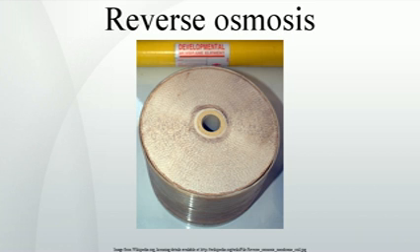The process is similar to other membrane technology applications. However, key differences are found between reverse osmosis and filtration. The predominant removal mechanism in membrane filtration is straining, or size exclusion, so the process can theoretically achieve perfect exclusion of particles regardless of operational parameters such as effluent pressure and concentration.